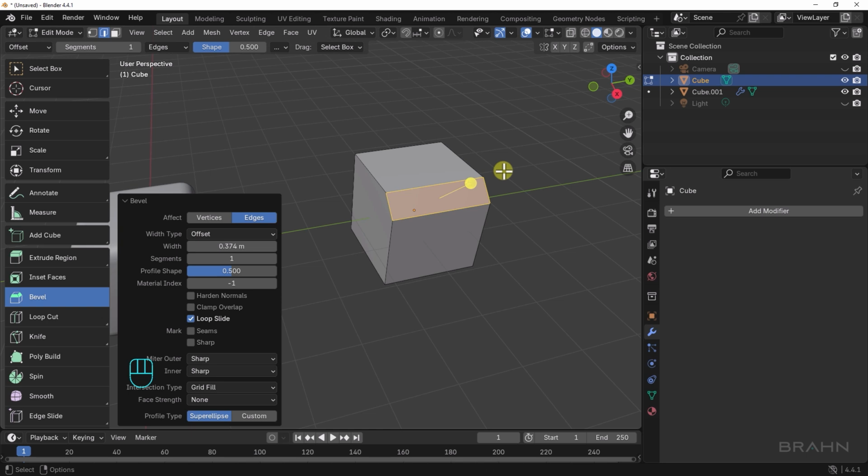Before clicking on anything else, note the Bevel label has popped up in the lower left. Let's open that up. This gives you a lot of options to modify the bevel. But like the previous Add pop-ups, this is a one-time event. You can always undo and start over, but once you change these settings and then unselect the cube, these will be permanent. Let's change some settings. Let's change the width to 0.3 like so.